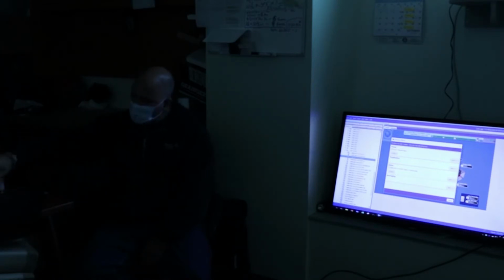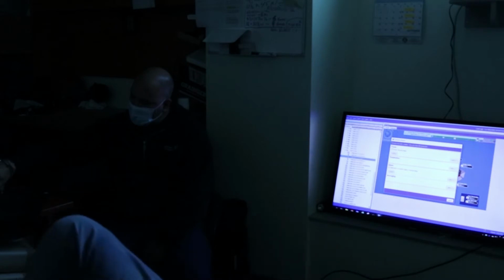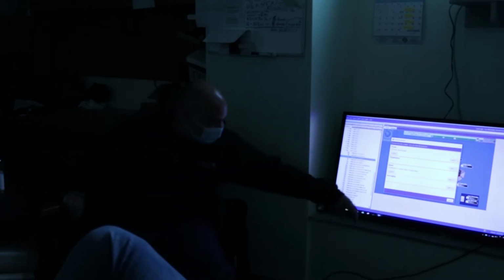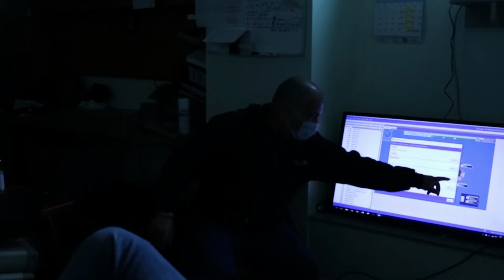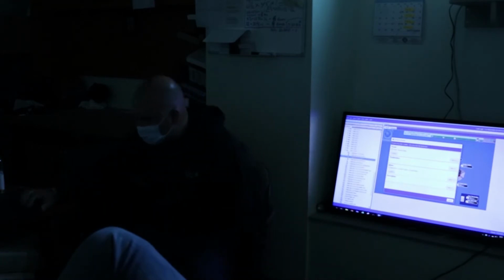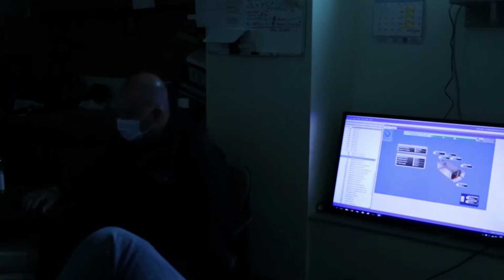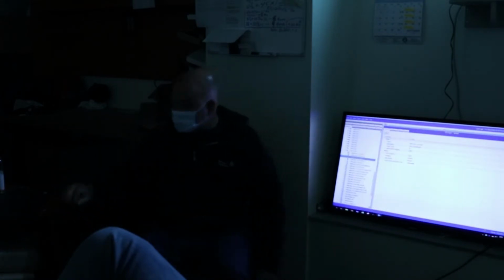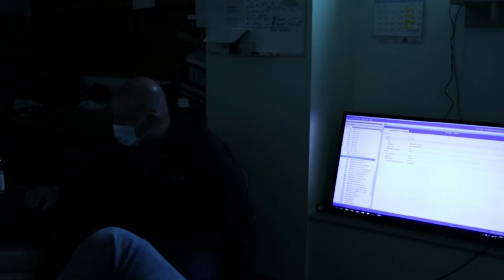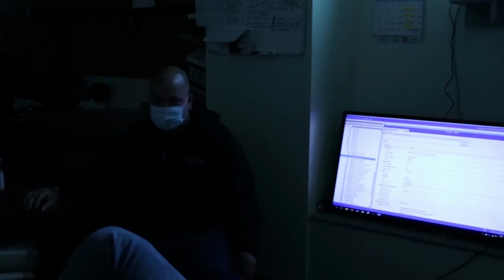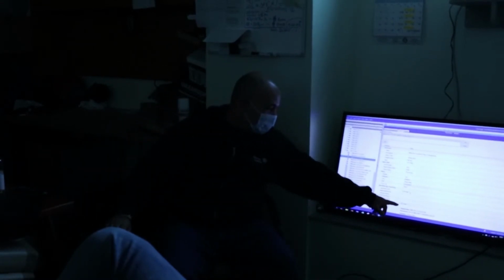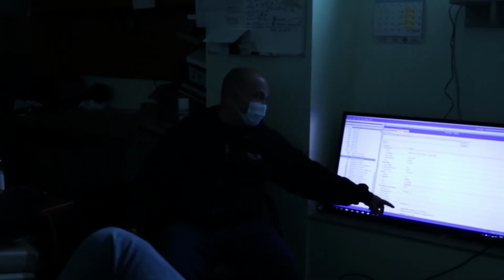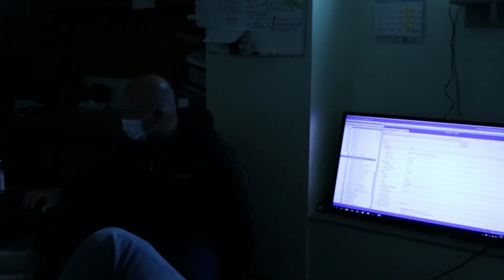Right here, you'll see there's an alarm there already. But if we want to add another one, we can. If you want to adjust the alarm that's there, let's drag the point over. See the alarm tab? We can click on the alarm tab and make an adjustment. Right now the high limit is set for 80 degrees, and the low limit is set for 65. You can edit this and make an adjustment.